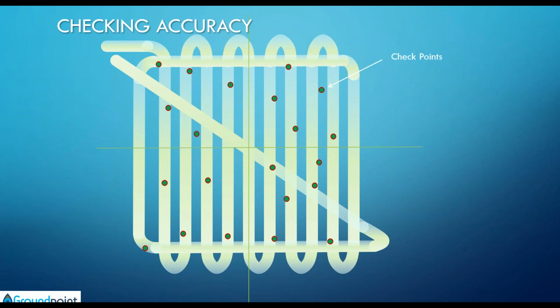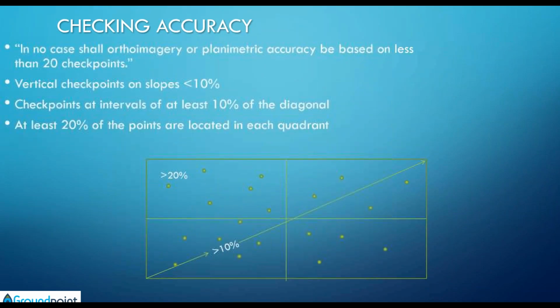And there's a whole set of guidelines that governs good and adequate checkpoints for this kind of statistical assessment. So all of the digital standards from the NSSDA 1998 forward say the same thing, right? Which is you have to have 20 points. You can't do an accuracy assessment and expect to get a 95% confidence interval on anything with less than 20 points.